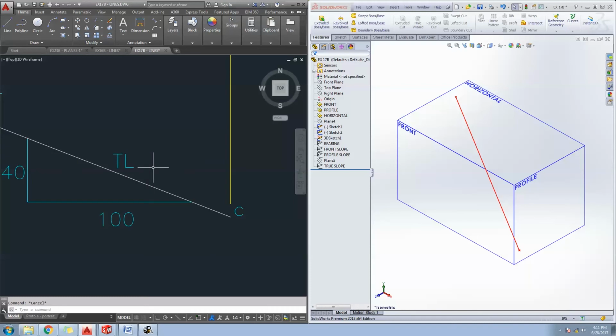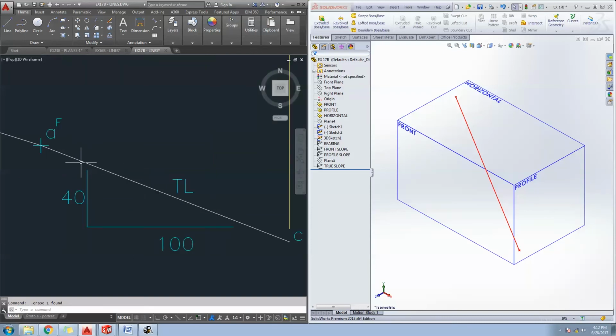So what we'll do instead is I'll offset this line. We'll offset it by, say, 1.5. I'll go that direction, take that, I'll trim, remove those lines, and remove that offset line right there, and now your grade doesn't actually touch the object.